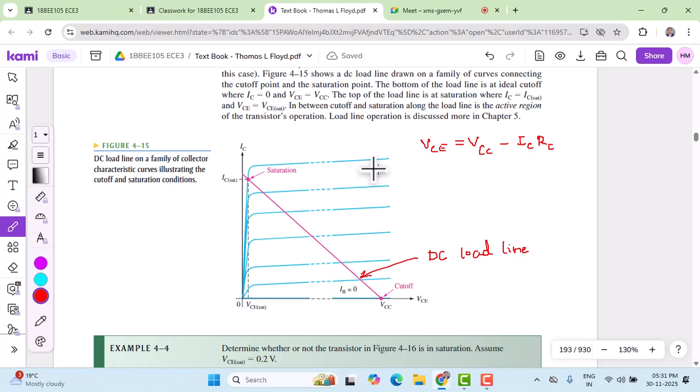So the maximum power dissipation reduces for every degree Celsius increase in the temperature. As temperature increases, the maximum power dissipation PD max decreases. This is a negative temperature coefficient that it has got. At what rate it decreases is given by the derating factor. Per degree Celsius increase in the temperature drops the maximum power dissipation by 2 milliwatt. That's the derating factor determined here. So this is about this.